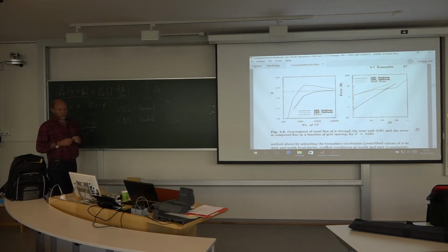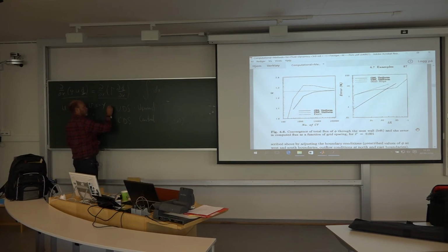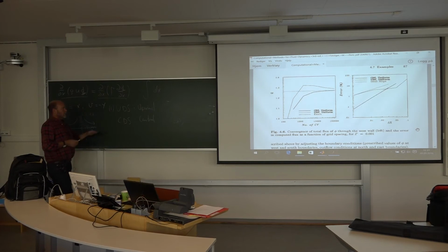The way you should think, in my opinion, is the following. Start with this one. Do a simulation here with the first order upwind scheme if you're only interested in a steady state solution. So this one is much faster. Then you will have a solution quite fast. It will be a bad solution, but still you'll get it.